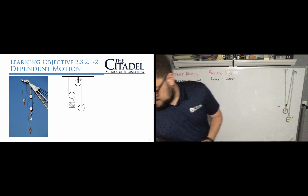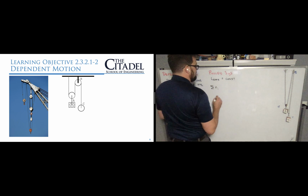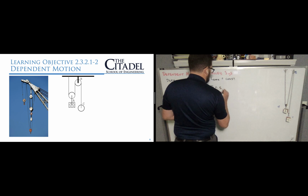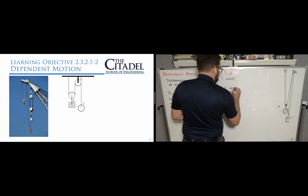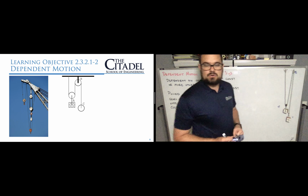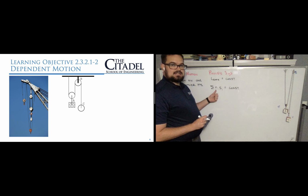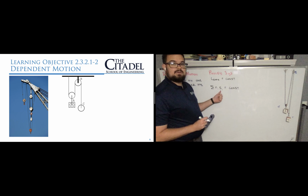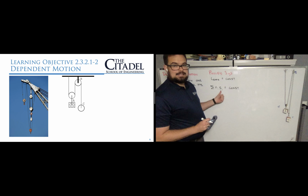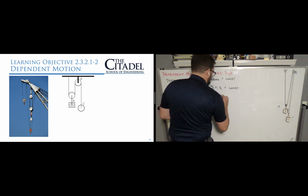Another way we can express that is using this equation, where the sum of the number of ropes at each moving point times the distance at each moving point is equal to a constant. That constant is roughly equal to the length of the rope plus or minus the little bits that curl around the pulleys. So this is the base equation. If we take the derivative of this with respect to time, the number of ropes stays constant, so that pulls out of the derivative. The derivative of position with respect to time is velocity, right? And the derivative of a constant is equal to 0. So it would look something like this.